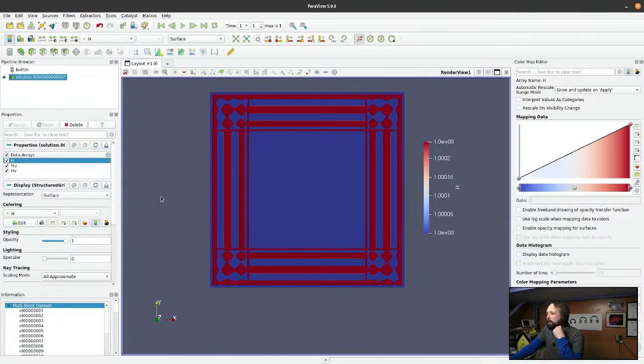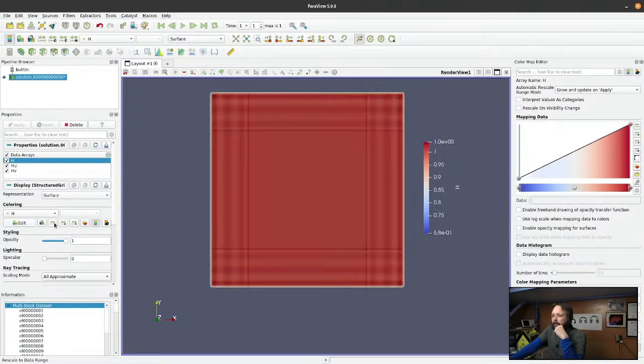Yeah, so what I'm thinking is going on here, so let's rescale this, is there's definitely an inconsistency at the boundaries. If you look at the color bar here, the red is now 1, and the blue values and anything lighter in color is going to be less than 1. And what it seems to be happening is at the boundaries, we're getting very, very small values that are being projected onto different polynomials inside of each element. And that will basically generate spurious gravity waves that will, if I were to keep running this, propagate to the interior and probably crash the code, because it'll keep generating this garbage.